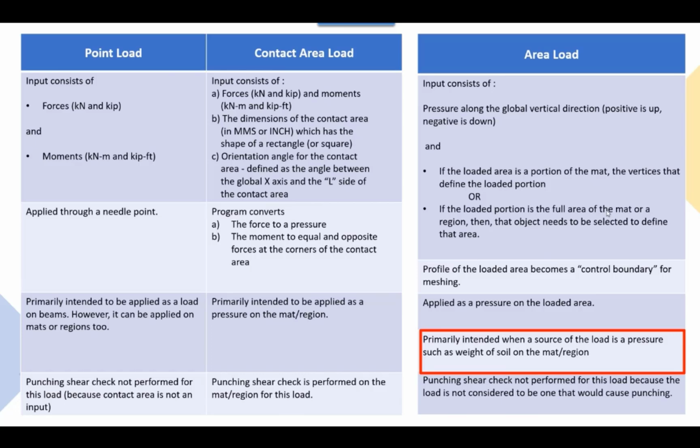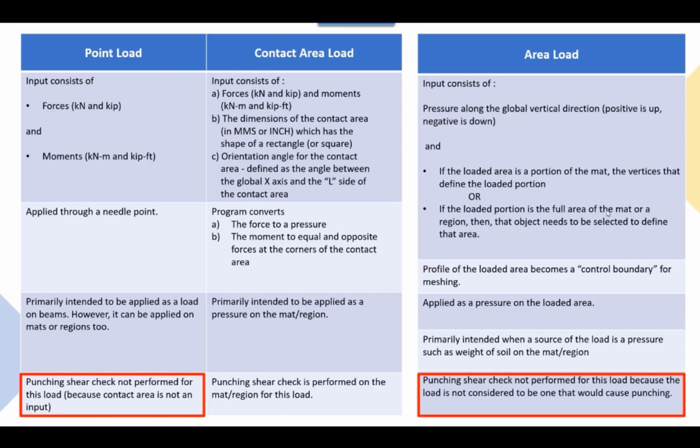Finally, let's discuss how punching shear checks are performed with each type of load. The punching shear checks will not be performed for point loads or area loads. Punching shear checks will, however, be performed on point loads that are applied to a contact area.